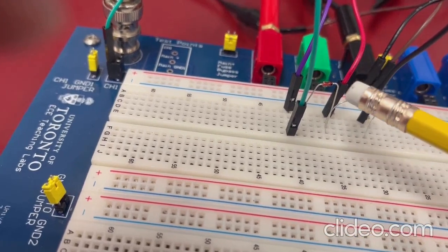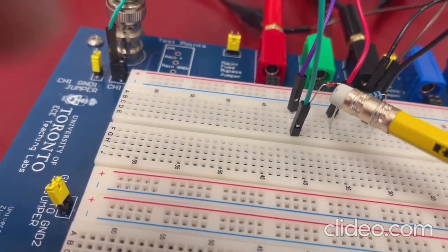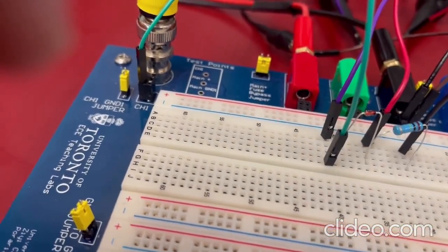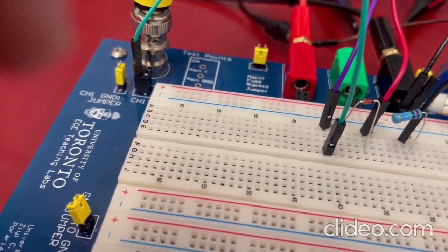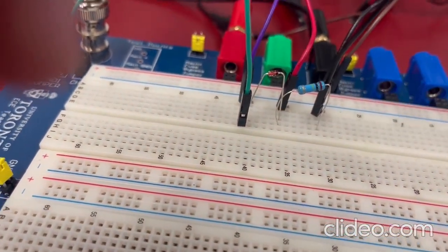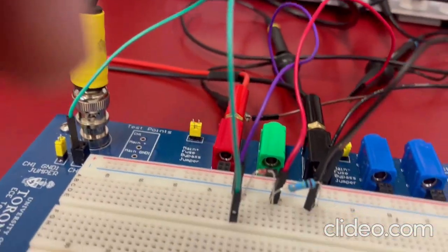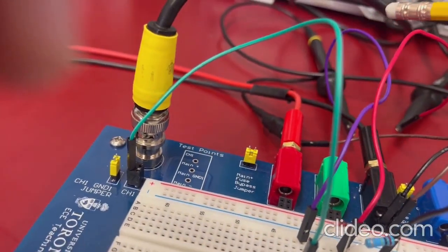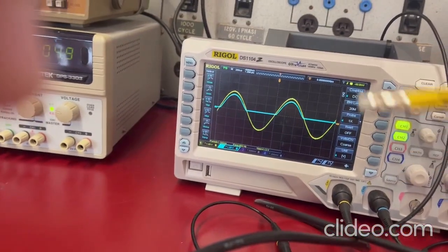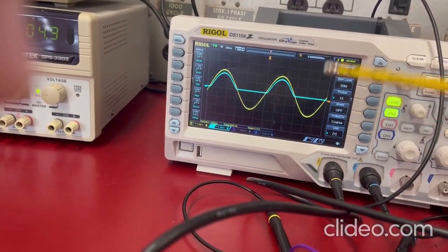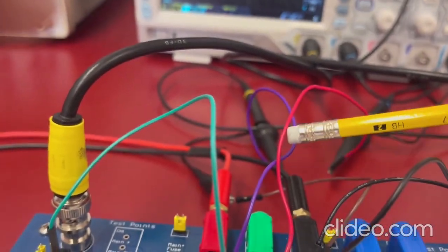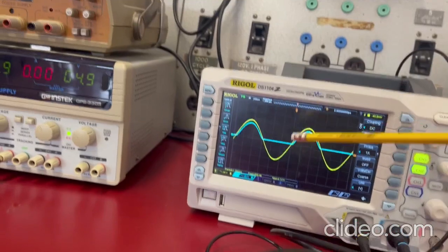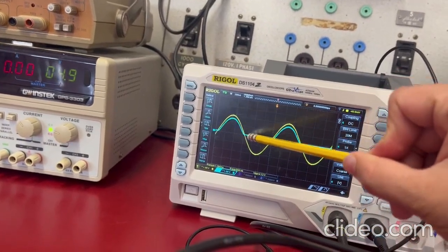One thing you need to consider is the direction of the diode. The N is with the black ring. Another thing you need to consider is the ground. I'm using the supply ground here, so this ground goes in here, which goes towards my supply. You can use the scope ground also. On channel 1, with the help of this magenta wire, I'm measuring my input, which is the yellow sinusoidal signal, with the red wire here. At the output of the diode, I'm measuring the rectified output on channel 2, with the cyan color, and you can see the rectified output.